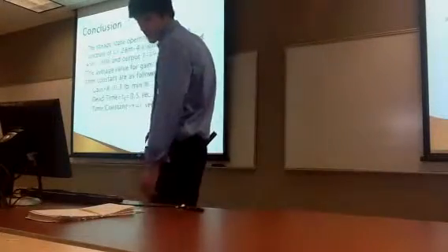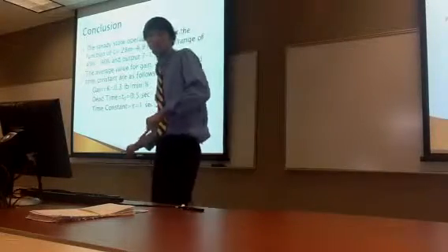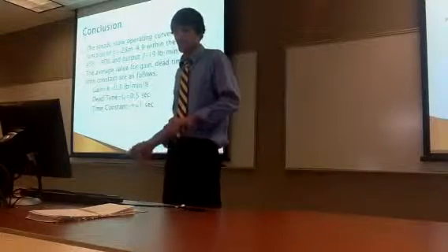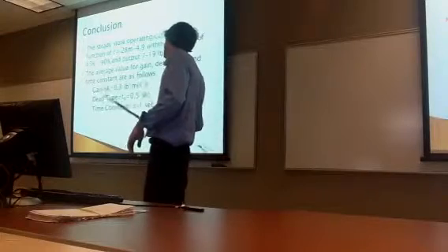In conclusion, the steady-state operating curve fit the function C equals 0.28 of the input minus 4.9, and of course our average gain, dead time, and time constants.